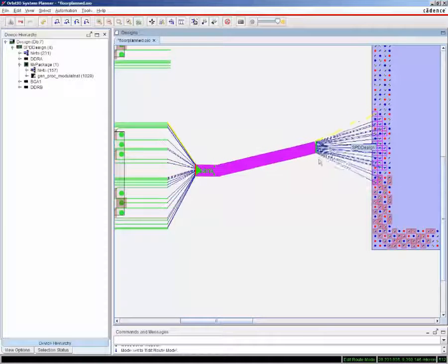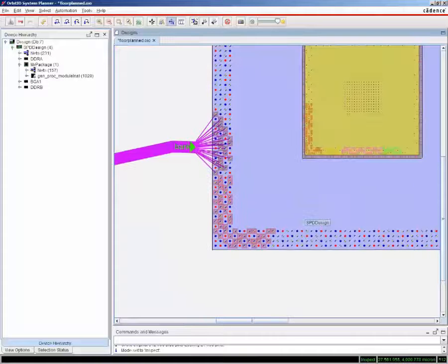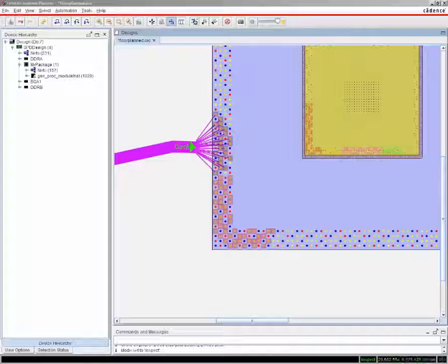The route lines come into the bundle in a specific order based on the breakouts and maintain the same order as they flow to the BGA. Pins are optimized based on the pin order in the bundle. This is especially significant if you don't have a straight line between devices.